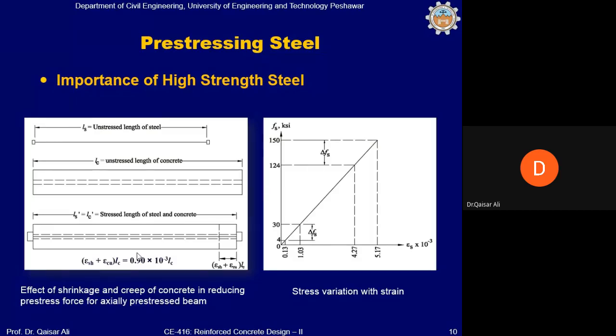And you know the creep phenomenon, that creep is change in the length of a concrete member at constant load or constant stress. तो कुछ लेंथ श्रिंकेज की वजह से कंक्रीट बीम की कम हो जाएगी और कुछ क्रीप की वजह से कम हो जाएगी, और स्टील भी यही चाहता था कि उसकी अपनी ओरिजिनल लेंथ आ जाए। तो अगर क्रीप और श्रिंकेज की वजह से कंक्रीट की बीम में जो रिडक्शन आ गई, वो स्टील की ओरिजिनल स्ट्रेचिंग से पहले की लेंथ के बराबर हो गई, तो स्टील में कोई स्ट्रेस नहीं रहेगा। Is that okay? Yes sir. ठीक है ना?